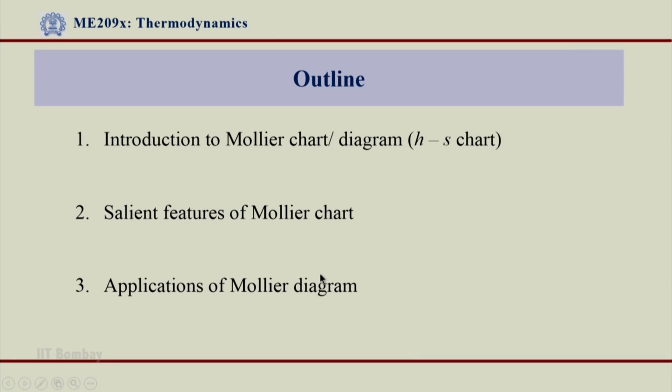I will also tell you one fact here, that this Mollier diagram I will not refer to all the time. It is actually useful to tell you how the process takes place: what is the state of the point when the process starts, and where does it finish. You can get a lot of information from that chart, but you can't get actual accurate properties from this. So, we will not refer to this Mollier chart all the time, we will not even solve the problems, maybe some simple problem, but mostly we will refer to steam tables only for acquiring properties at different states of water.